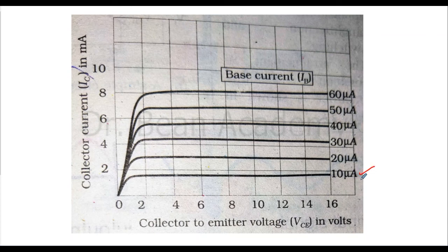So now the current is there. I adjusted a suitable voltage VBE from the input curve. So when I set this voltage across base and emitter, the current from the base will be here, and we just saw that this will be constant. Once I set a suitable voltage, the current from the base will be 10 microampere. So now it is fixed.